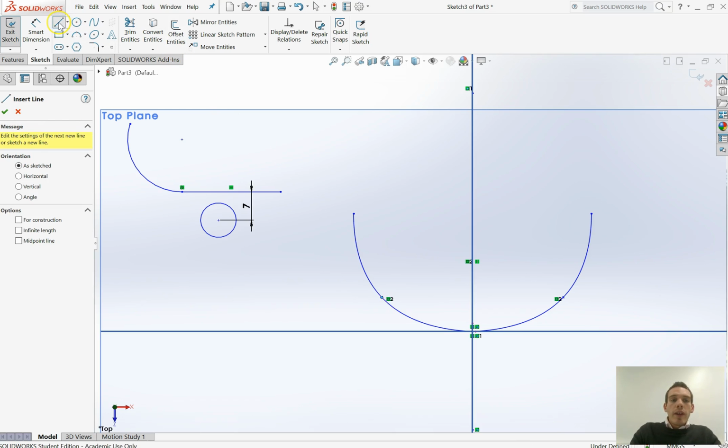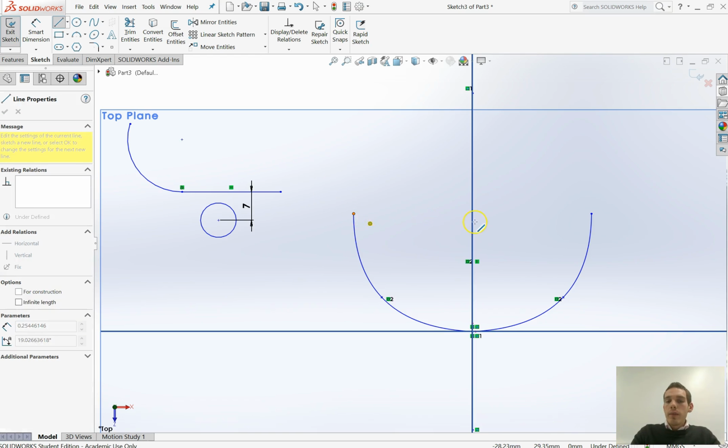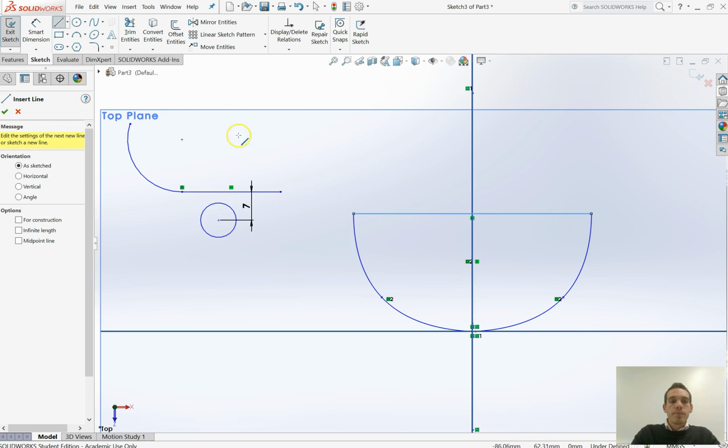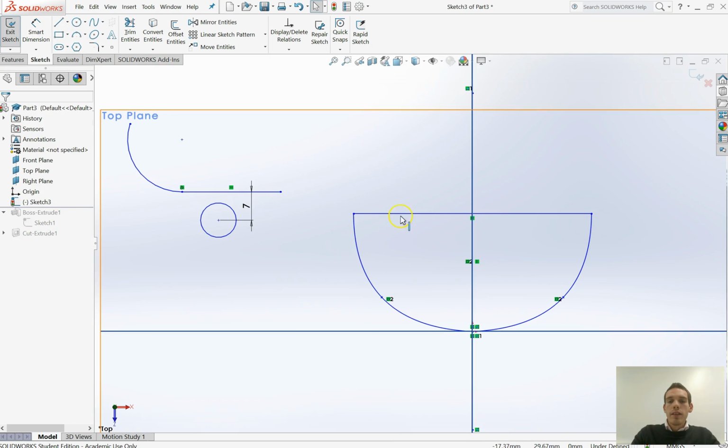Now, to extrude anything, as I said, we need to make sure it is effectively watertight. So if you want to extrude something, make sure you join up those dots so you create a single contained volume. Click the tick to accept that. Go and select, and you can see that that is now a contained volume that we could extrude. We've got these random bits here. We can't have just random bits lying around.